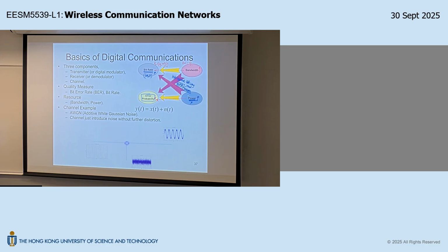So in this case, although you are operating in a linear region on average, right? But when you have this peak, it may exceed the linear region and enter into the distortion region, right? So the output signal will be like this, but when you have a peak, this peak will have clipping. Okay? So you may have clipping. So the issue is when you have this kind of nonlinear distortion resulting in clipping.